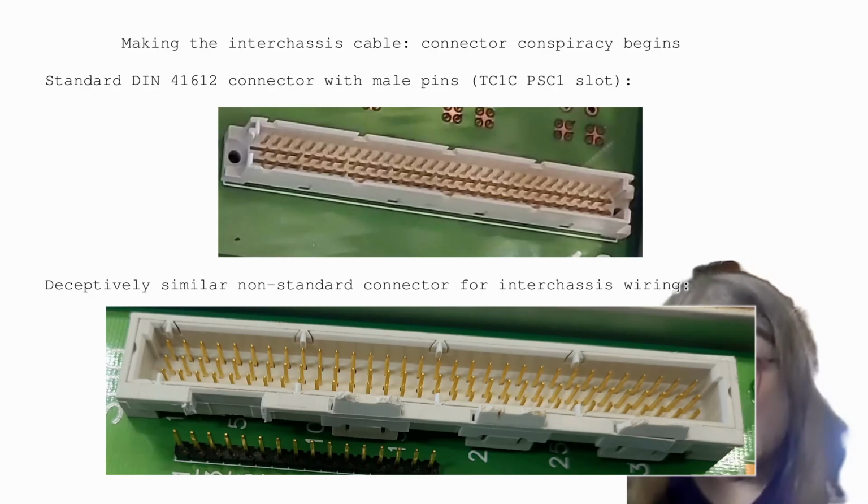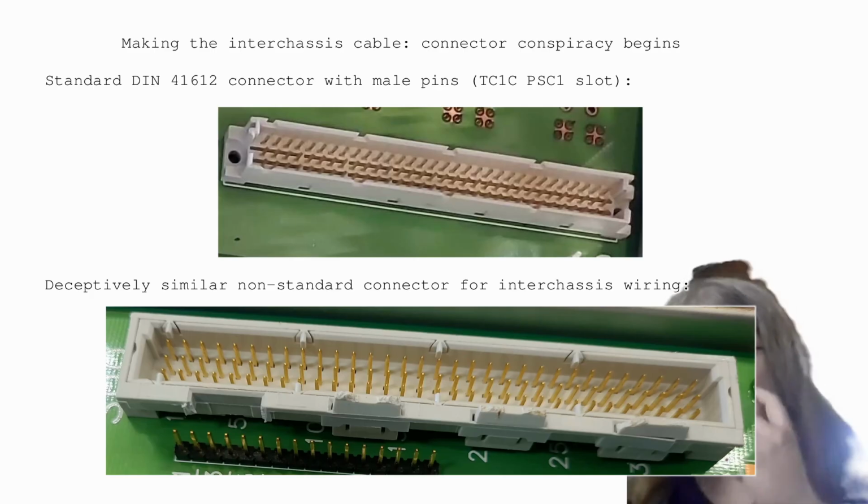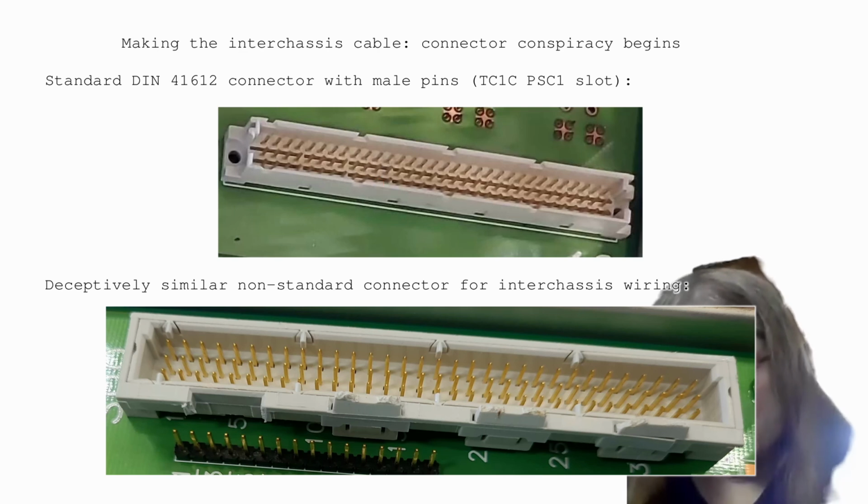At first, it looks deceptively similar to a standard DIN 41612 connector. For comparison, this is an actual DIN 41612. This is what they use also for all of the cards and the modules as they go into the chassis. The connector at the very back, your backplane connector, is a DIN 41612. It's the same type of connector that's used in the VME bus systems. So it's an old-fashioned, pretty standard thing.